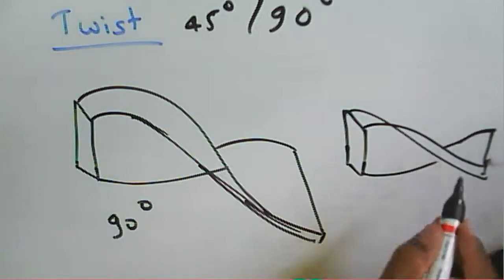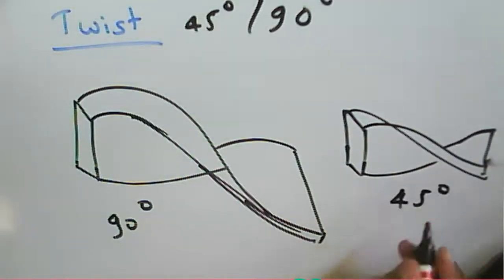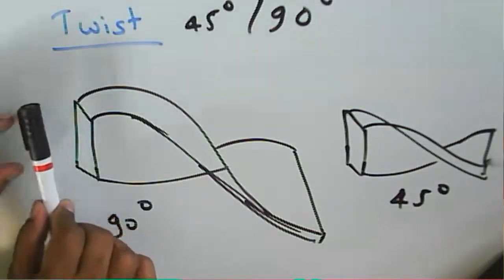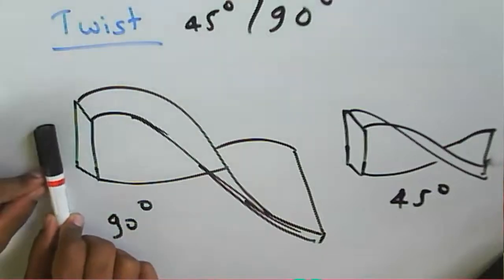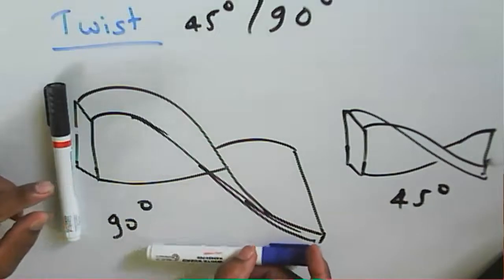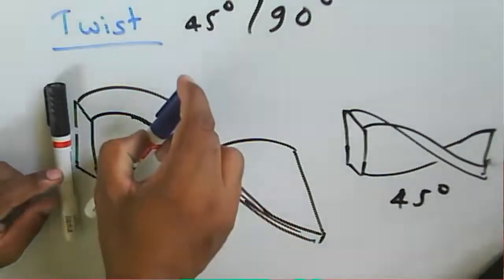And this one is a 45-degree twist. Likewise, that is about a twist. It is used to change the polarization. Suppose we have the waveguide and the signal is propagating, and we want a 90-degree twist. So there are 90-degree twists and 45-degree twists.